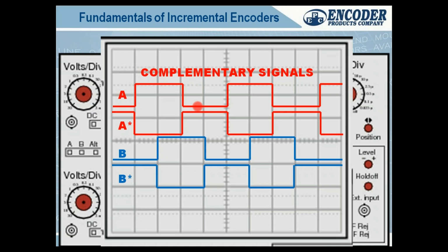How we recommend it anyway, everybody's got a little bit different, but they're all about the same. Manufacturers say if you're running more than 30 foot of cable, you want to run complementary signals. If you're working in a warehouse, stretch wrap machines, anything with a lot of static, just don't even play around with it. Very often there's no cost. With us, there's no cost to go to a complementary output. Your cost increases only in the cable. You're going to have to run cable with 2 more conductors, but it's highly worth it for rejecting noise.